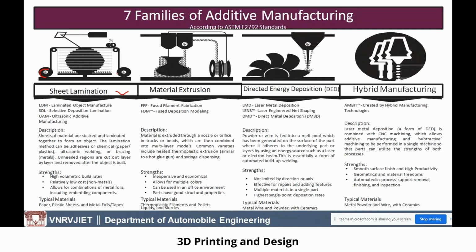The first layer of this raw material is moved and placed onto a platform, and then that first layer is exposed to a laser beam, again a laser beam or UV light. You can see here in the middle, this is the diameter of that sphere. Wherever you want to project that laser beam, you can control with the help of the 3D printing machine.